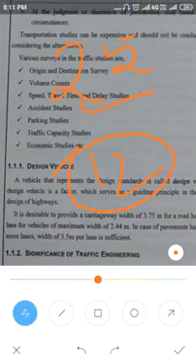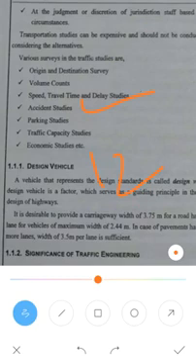For this period of time, the number of accidents which occurred at various points will be collected, along with what precautionary steps can be carried out, or whether any alternate roadmap is available to avoid such accidents. That can be done by surveying in the traffic studies. So that is the accidental studies.